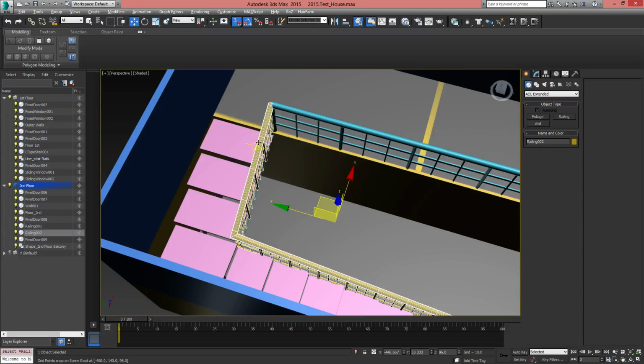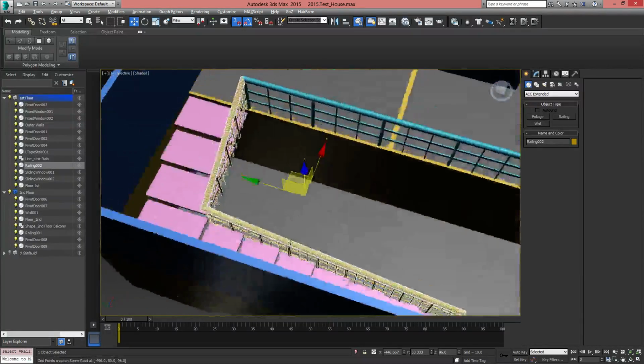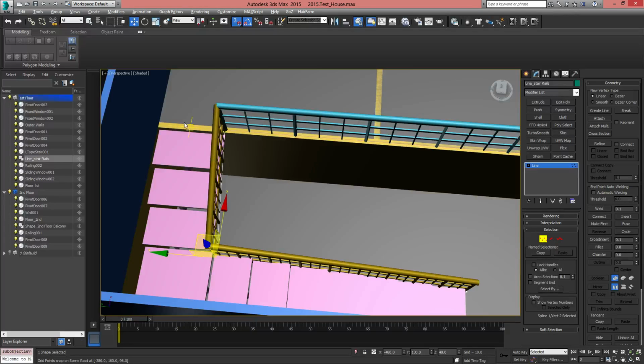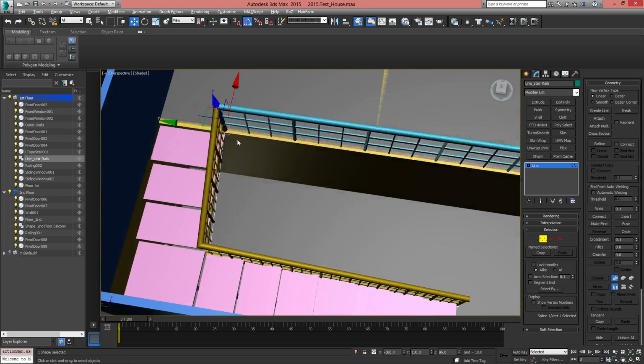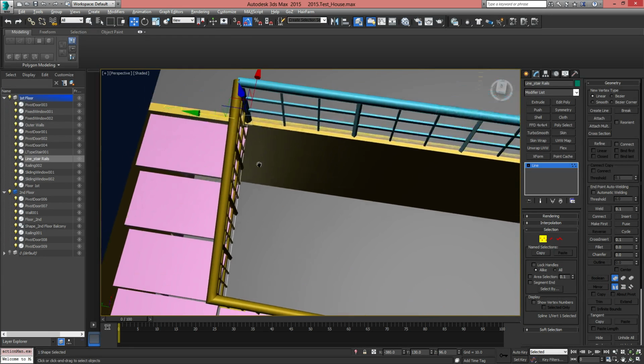And this is the second railing here, so I need to move this up to the first floor, or down to the first floor, because it starts and connects from the first floor to this. So I'm going to go back to the line it's actually on, and I just need to move this over just a bit. Not that much. I'm going to turn off my snaps, because my snaps is going to adversely affect how I want to do this, because it's snapping by grid points of 10, and I want to move by a smaller interval.